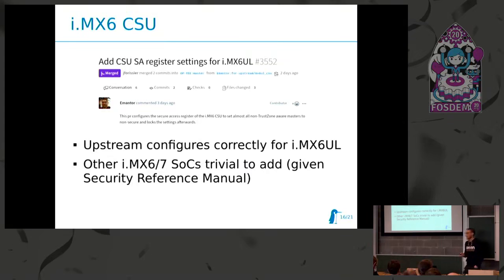I will probably just hack the GPU driver to try and issue a DMA request, but you could also probably do it using the UART DMA capabilities. So the SDMA firmware should be able to do DMA transfers there. So I will test this, and then I will submit more pull requests to fix this if it doesn't work.